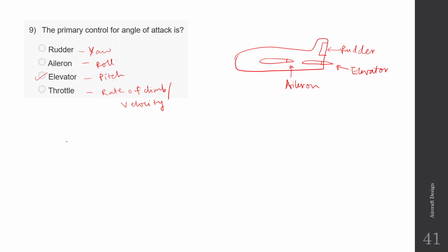If you look at it from the top, we'll do it later. So your wing is usually situated close to the CG. Okay, the CG is a little ahead of the wing aerodynamic center. But the wing is usually close to the CG. So if we place any control surface on the wing, it will have less effect on the longitudinal stability.